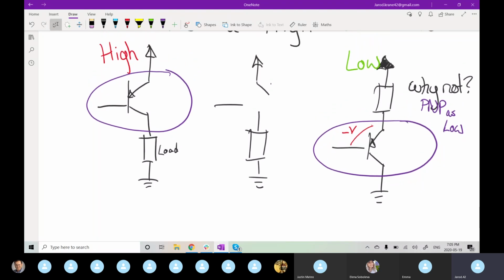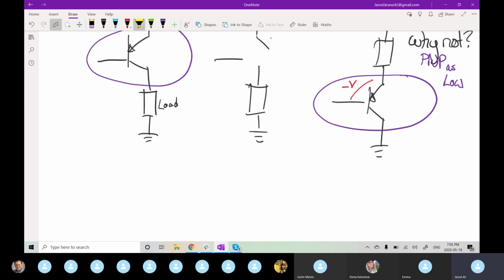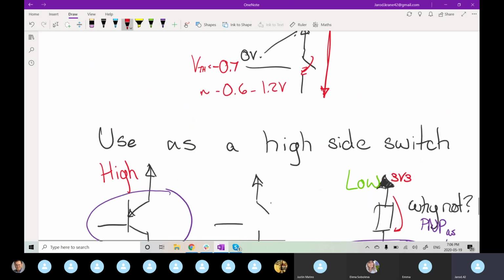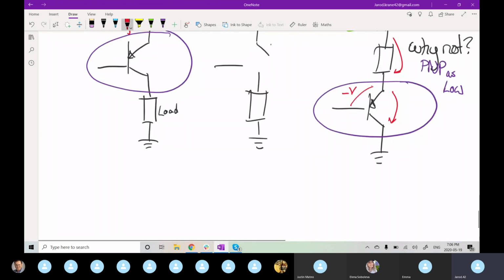But we will see that if we start off at 3v3, your load is going to create some voltage drop. And then our transistor, because of its internal threshold and its voltage drop, which is some 0.7 or whatever 1 volt that it is. And then at this node, we're obviously tied to ground.